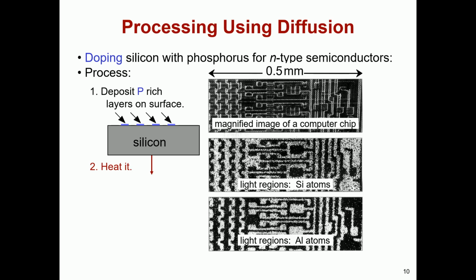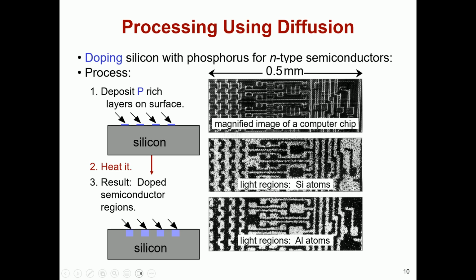increases with temperature. Remember that vacancies move outward from the bulk. So conversely, phosphorus atoms can diffuse inward. By patterning the phosphorus layer, we control where doping occurs. Through thermal diffusion, phosphorus penetrates into the silicon, creating the doped region, which is essential for semiconductor device operation.